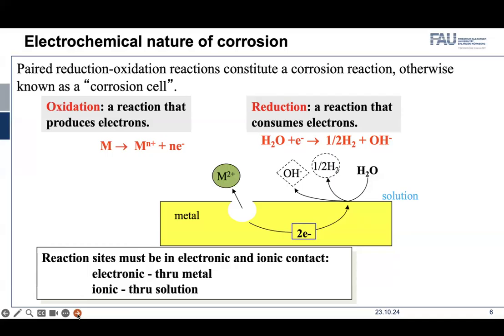But if you look at it microscopically in a shorter time span, then the electron sources and sinks are moving randomly across the surface. But that is only assuming that our metal is fully immersed in electrolyte. Because in real life, the corrosion still sometimes or often occurs locally because, for example, we need a droplet of water or something to give the electrolyte.